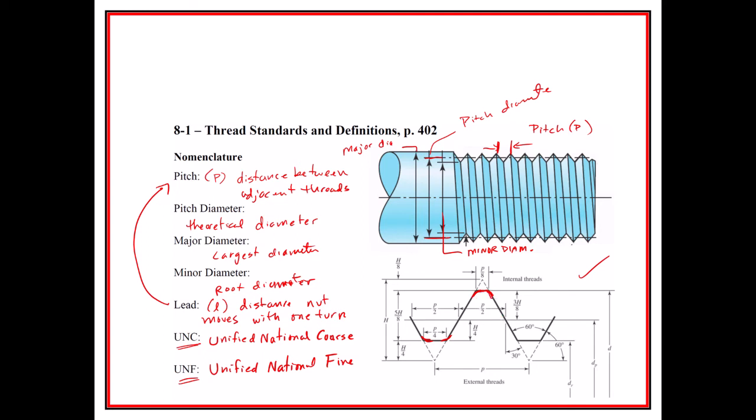But most threads aren't cut, but instead they're kind of forged, right? So your typical production threaded piece isn't cut, but instead I'm trying to think of the correct words. It's like hot forged, where we actually roll. That's what we say. We actually roll instead of cutting most threads, and we'll see why that is. And the act of rolling actually puts little fillets everywhere and rounds the thing off.